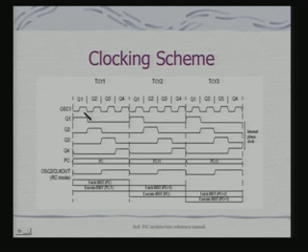This clock is actually internally divided or split up into 4 quadrature clocks. So, I am showing you Q1, Q2, Q3 and Q4. The whole instruction execution is managed by these 4 quadrature clocks. So, what you find is, just look at here, you have got your first cycle where you actually fetch an instruction. Let us start with this. In this, I fetch an instruction. Now, once I fetch the instruction, I have shown it within the bracket saying PC. That means I am fetching the instruction which is being pointed to by the program counter.